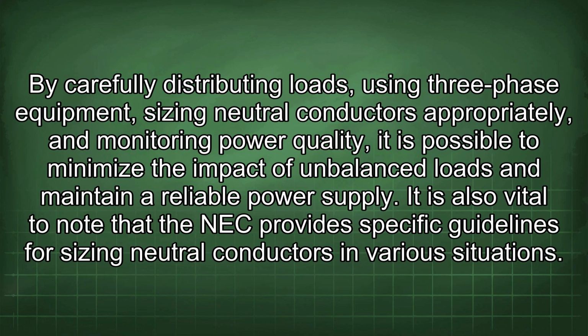By carefully distributing loads, using three-phase equipment, sizing neutral conductors appropriately, and monitoring power quality, it is possible to minimize the impact of unbalanced loads and maintain a reliable power supply. It is also vital to note that the NEC provides specific guidelines for sizing neutral conductors in various situations.